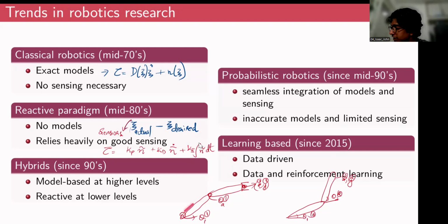So we repeat these experiments for multiple such instances, recording for any given x and y what the theta 2 and theta 1 should be. And then we try to create a map, or maybe a regression model, or probably plug this into a neural network, so that for any input x and y, the model would give you the corresponding outputs in terms of theta 2 and theta 1.